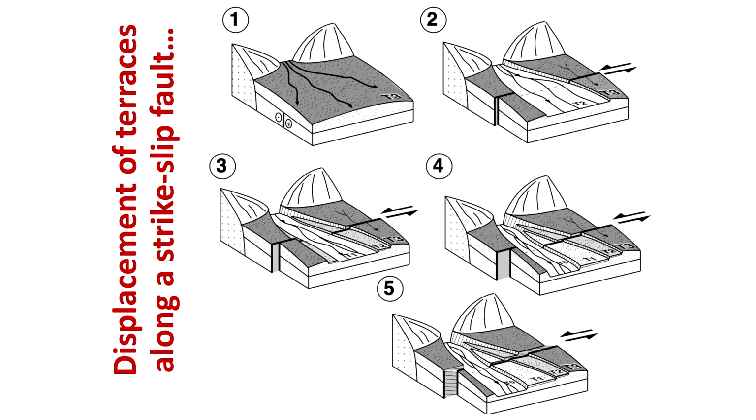These are the symbols: the cross is the area which is moving away from us, and the circle with dot is moving towards us. Okay. So, in some literature you will find symbols like this. You have a fault here and they mark this cross, and then you have a dot here. That means this portion is moving towards us and this is away from us. Okay. So, this is left lateral movement.